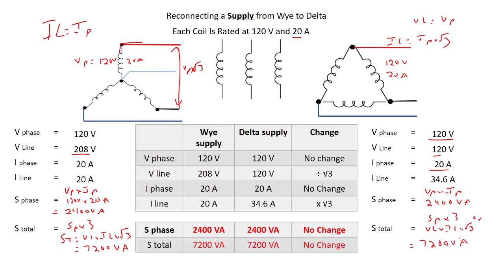So, a little summary chart. Basically, the apparent power produced in each phase is the same, and the total apparent power that this thing can put out is the same whether this generator was Y connected or delta connected. Same output VA capability. The difference is the line voltage in delta is root 3 smaller, but the line current is root 3 higher. So that's why it has the same output VA.